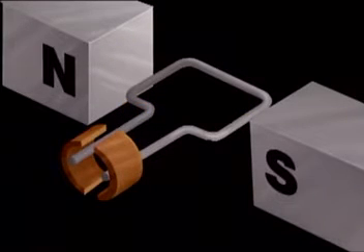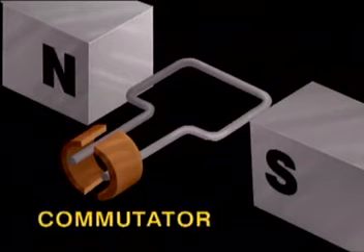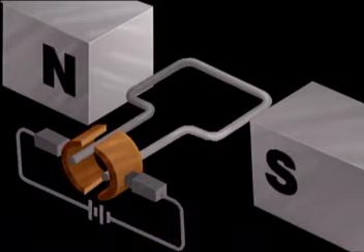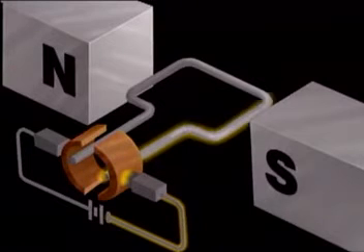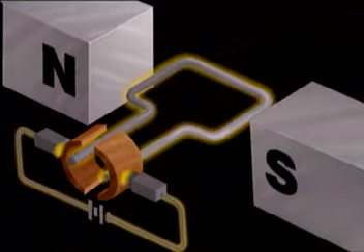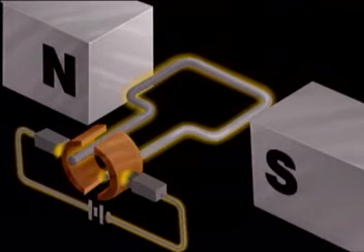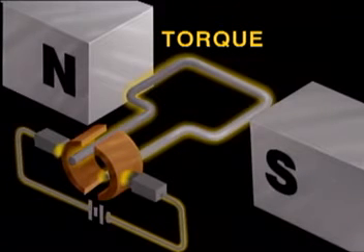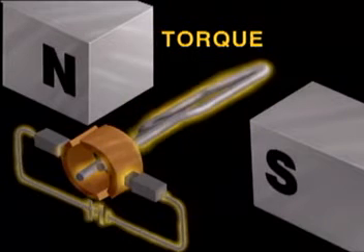Around the base of the armature is a split copper ring called a commutator. Outside the commutator are two brushes that slide along the commutator and provide an electrical connection for current to the armature. As the armature is supplied with current, its circular flux lines interact with the magnetic field's flux lines, as you saw earlier. The armature is designed so that the magnetic push, or torque, which results from the interaction between the two fields, causes the armature to rotate between the two opposite poles of the magnets.